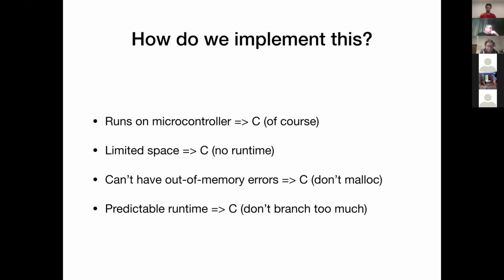Well, it's got to run on a microcontroller, so probably C. It's limited space, so probably C. If we don't use malloc, well, probably C. And we can get predictable runtime from C, which we can't necessarily get from a garbage collected language, right?